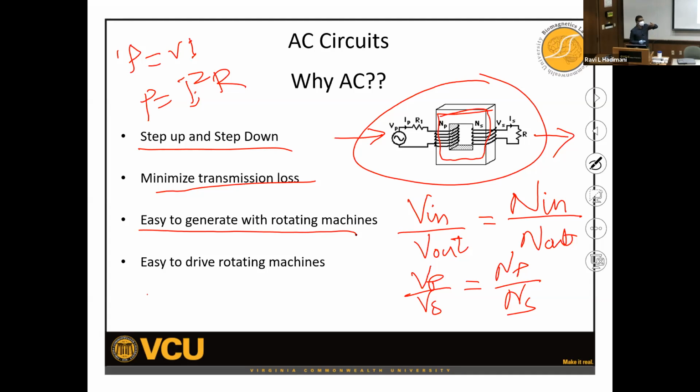By doing that, you are switching the poles, and you are switching between the repulsive and attractive forces, which makes the motor move. If you don't have AC power, you can still have DC motors, but you will have to have contact brushes. You'll have to have a slightly different mechanism, which is prone to wear and other problems.